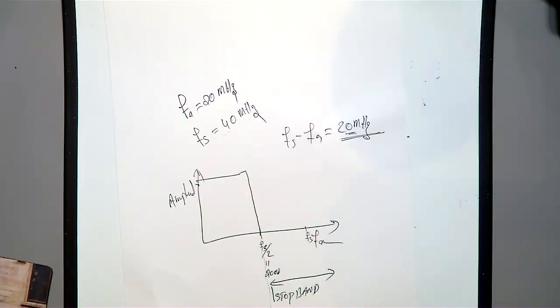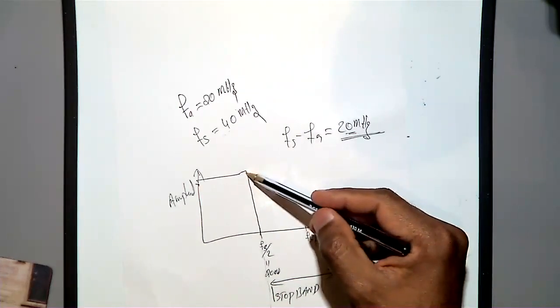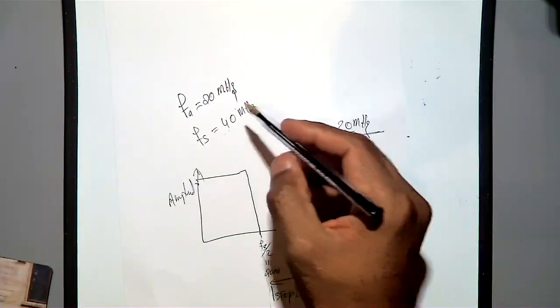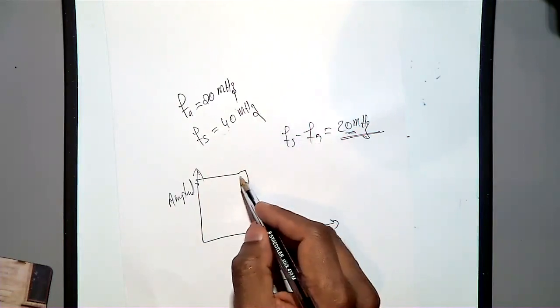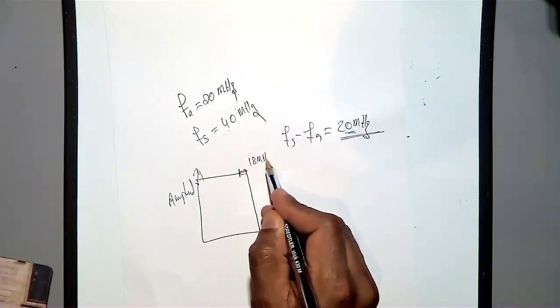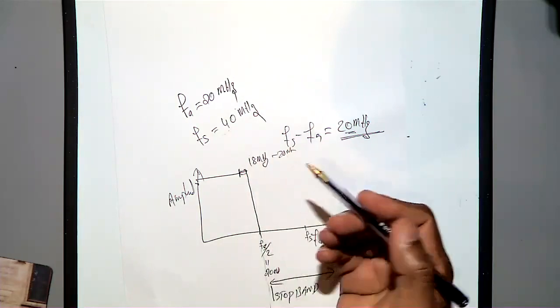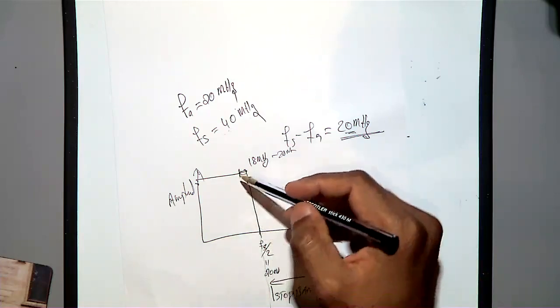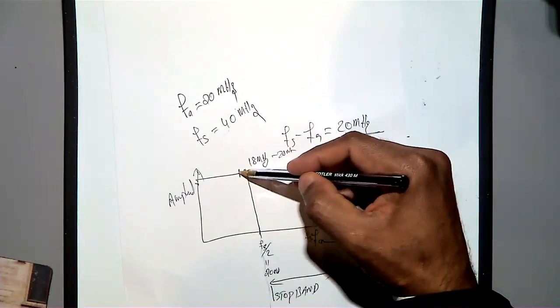But if you don't have a tight design like this, then you can have something like this. In your case, the design is tight. So what I would recommend is your minus 3 dB point can be between 18 megahertz and 20 megahertz. So it could be maybe 18.5. You know what I meant? Your 3 dB, and then your pass band.